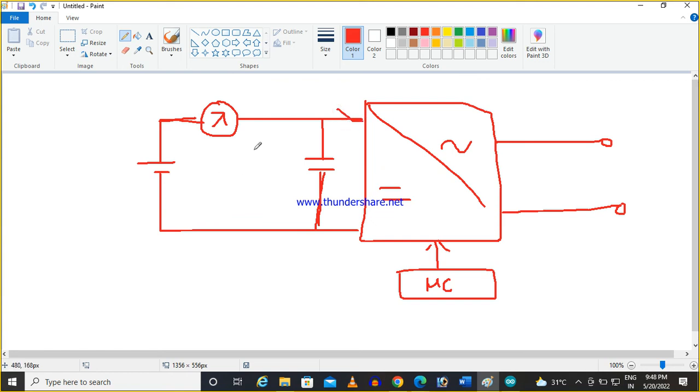Now you precharge the capacitor, give the triggering pulse from the microcontroller, and switch on. Now the load is open, so this ammeter should not show any current. Ideally it should be 0. That means there is no short happening, that means your PWM is correct.